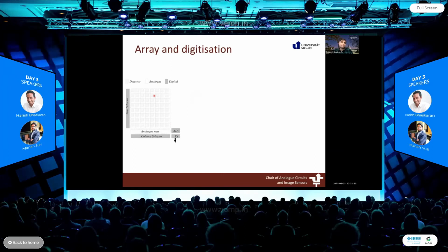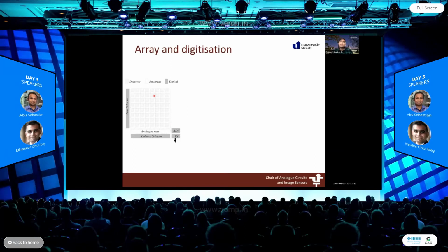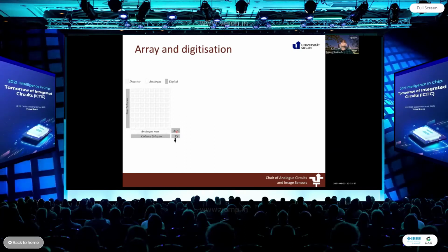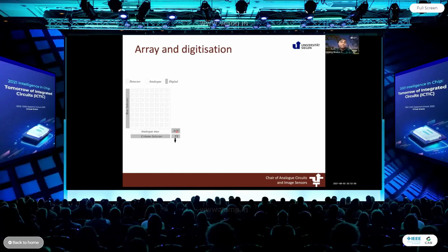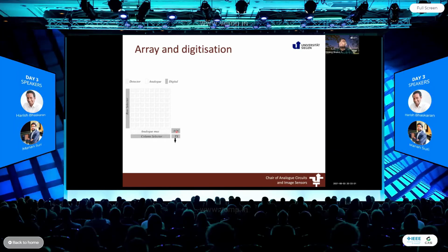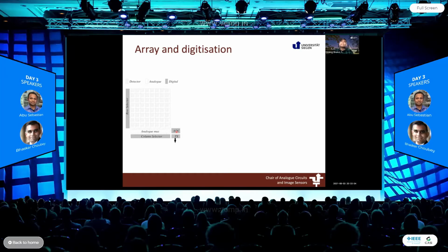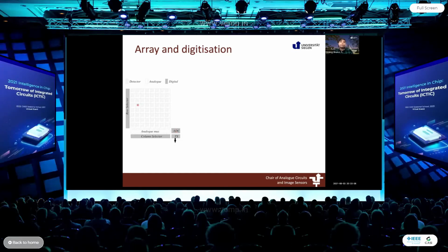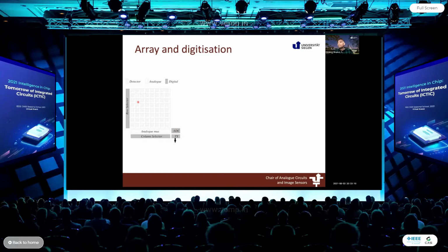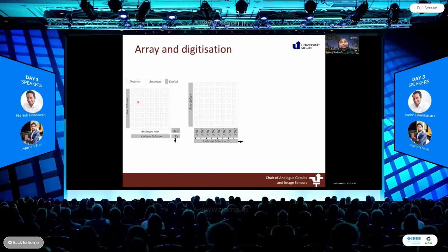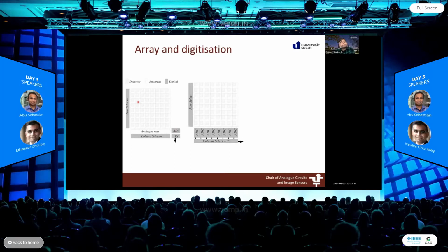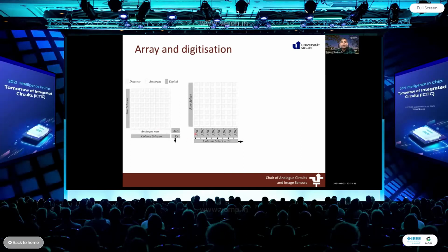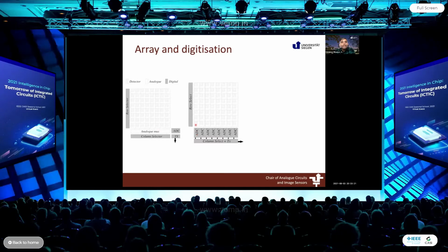So if you have 10 megapixels and you want 30 frames per second, which means your ADC should be going at 300 megasamples per second, which A is a bit challenging, but B, an ADC going at 300 megasamples per second is also going to produce heat. This heat in turn is going to heat all my pixels and increase the leakage current of the diode. So, from there to an ADC per column, and that's a good design, because then one ADC only has to convert